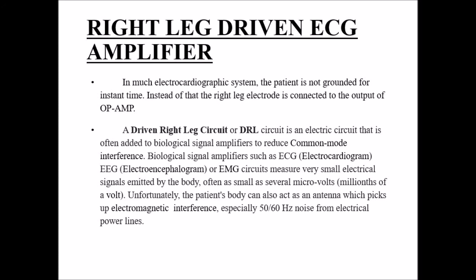The reason is, in many cases the reference electrode must be connected to the ground or to the right leg, in case of ECG, and in case of EEG this value is to be considered. We will see this right leg driven ECG amplifier in the next class very clearly. Thank you.